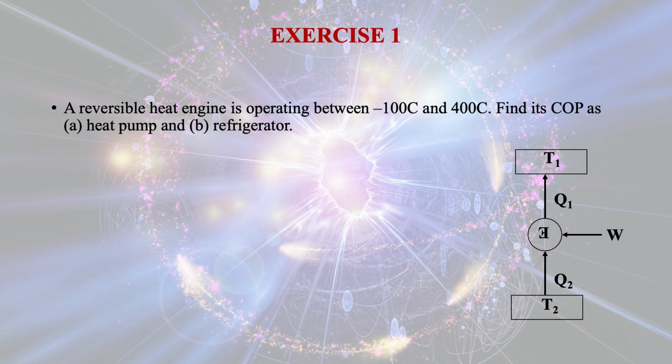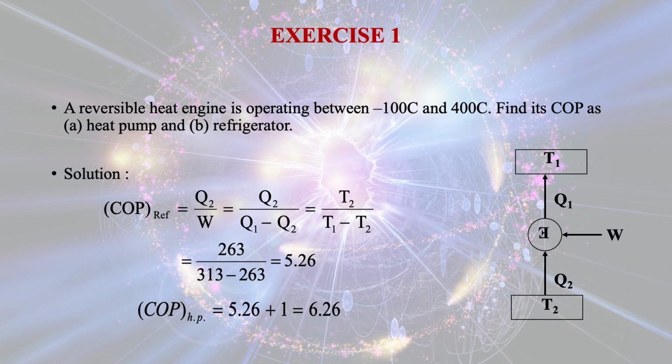But we know very well the expression for COP of refrigerator is equal to T2 divided by T1 minus T2, where T1 is the temperature of the source and T2 is the temperature of the sink. But in this case the lower temperature is T2 and the environment temperature is T1. T2 is given as minus 10 degrees centigrade, T1 is given as 40 degrees centigrade.